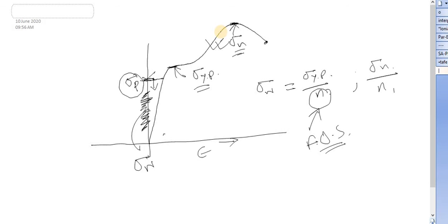But you should learn why you need to know this stress strain diagram, what the implication is in your engineering life, or why it has been asked in the examination. The reason is this: you need to find this working stress, and it is not possible to find this working stress by measurement. It is not impossible, but it is difficult. To eliminate the difficulty, you rely on the yield point or the ultimate point, because these are visible points.